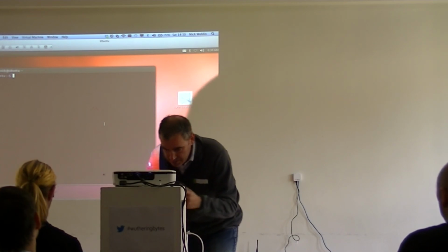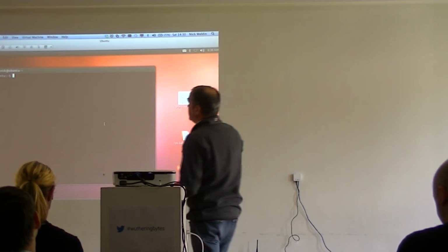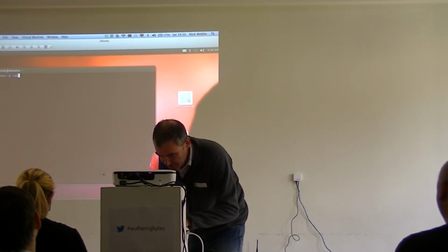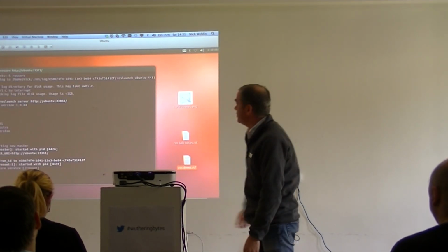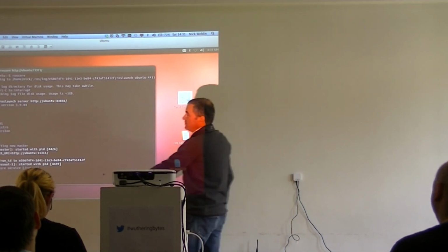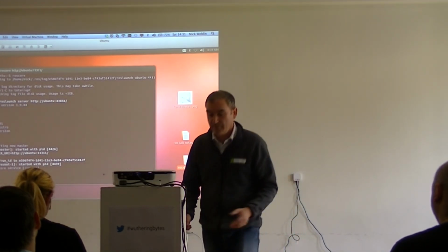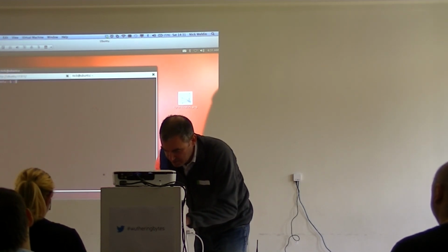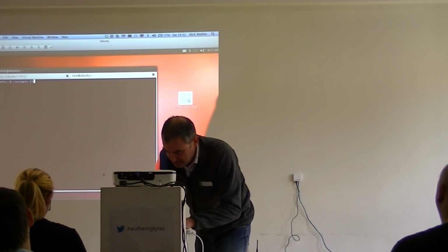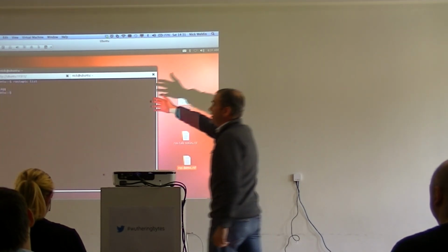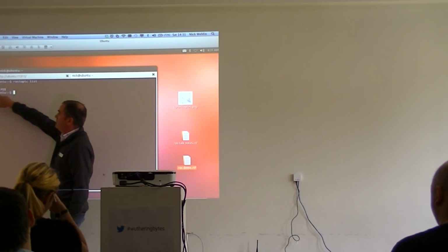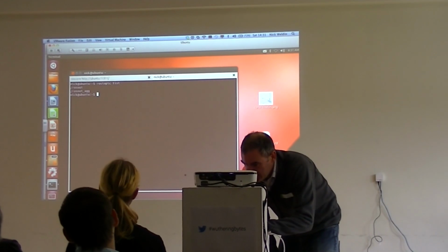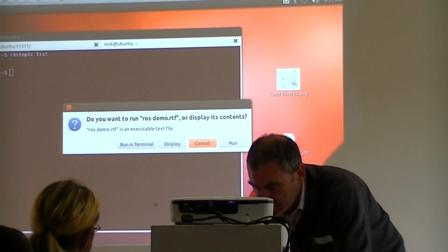Okay, so you've installed ROS on this machine and you launch stuff from the command line. If we want ROS running, we get roscore running. So we've now got the ROS server running. I'll open a new terminal window and ask it to tell me what topics it has. So the server's running. There are only two things running at the moment. Nothing much is going on. Basic server.